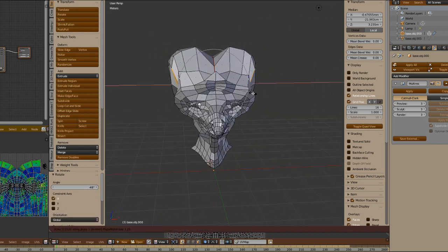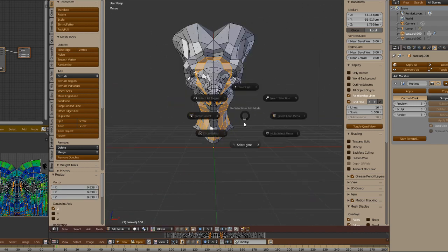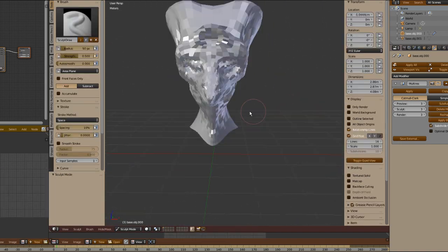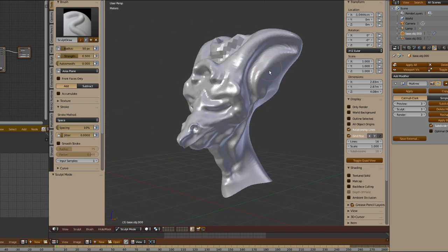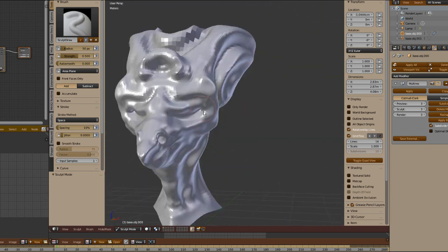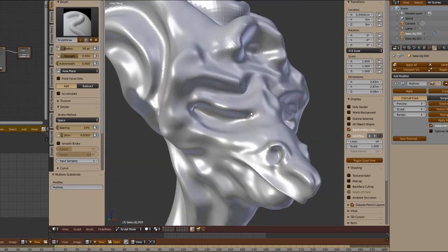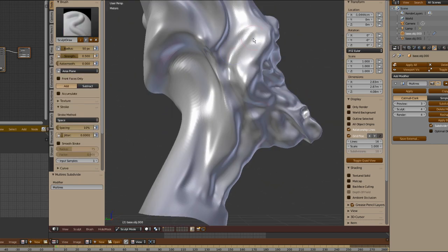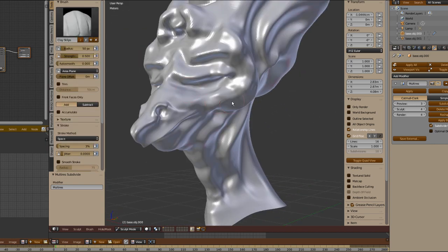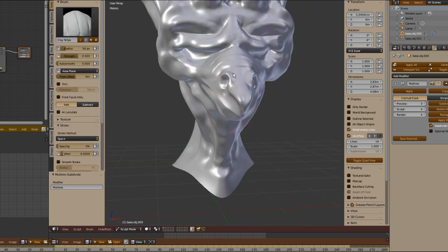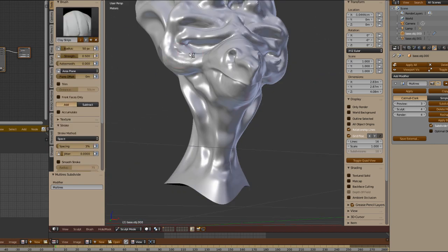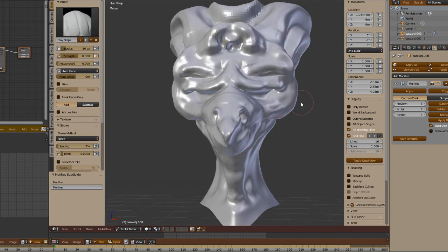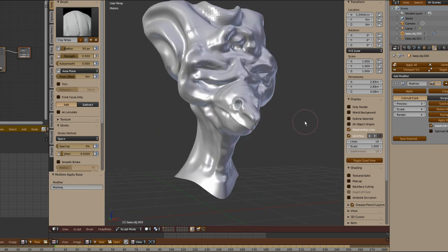You may also realize that at some point I enter edit mode and use proportional editing with variations of influence to move, rotate, or resize the polygons in a fast and global way throughout the mesh. These changes will be accepted normally and without any problems in sculpt mode. There is no problem whatsoever, and the brush deforms the surface of the mesh perfectly and with excellent quality.